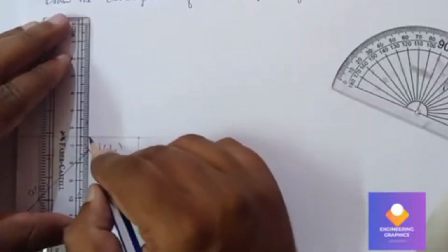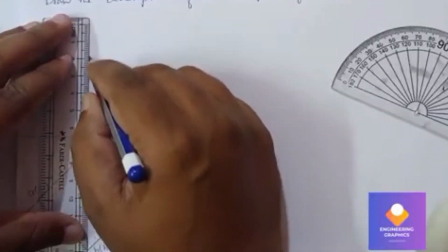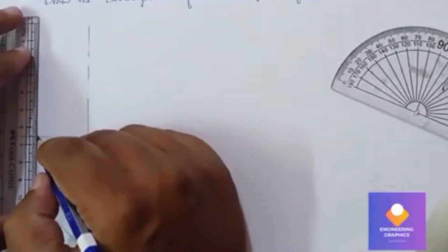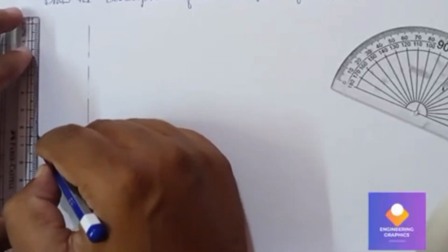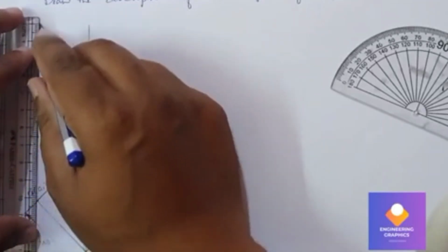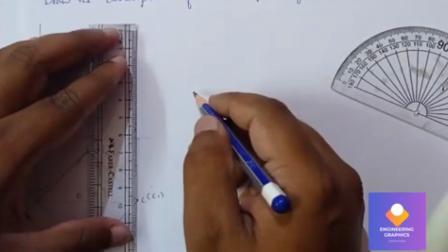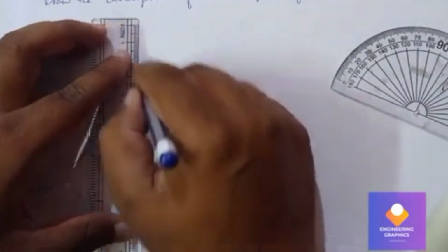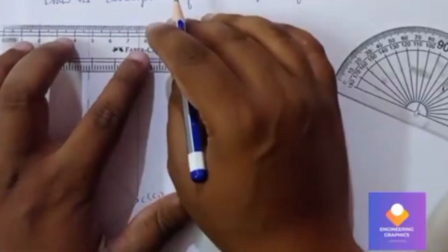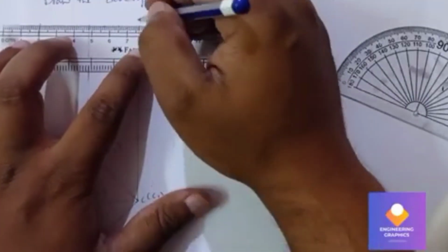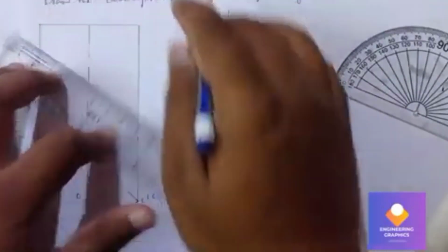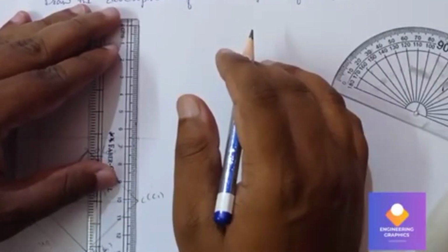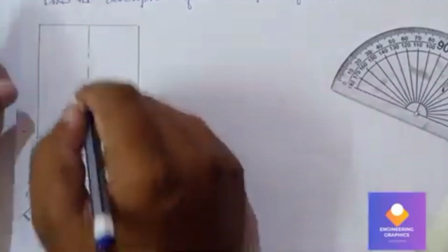Using the axis length we can draw the front view. The front view will be a rectangular face here. So we are constructing a rectangular face. Take 65 and construct it, and show the dimension on one side.